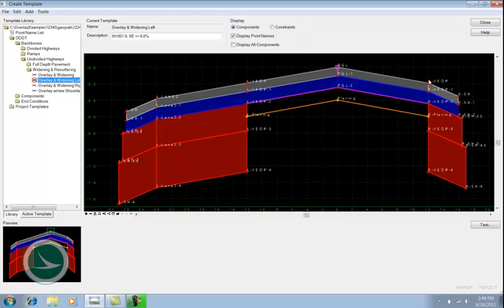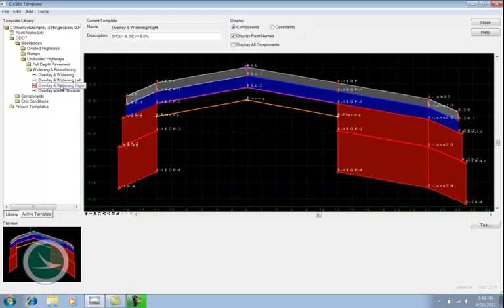On the right side, I don't have any saw cut. It just goes right to the edge pavement and adds a new shoulder. So that's the difference on this one versus the first one, is there's no saw cut on the right side. And again, this could be either an edge pavement or a saw cut. And then the widening to the right is the opposite, no saw cut on the left, and I've got a point that could be used as the existing edge pavement or the saw cut location.